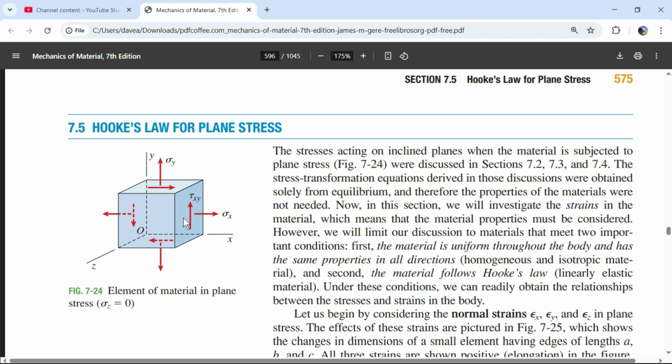All right, so this shear stress is on a face, and this face is in the positive x direction, and this shear stress is in the direction of the positive y direction. And so that's what we call a positive shear stress. And then over here, this one's on the negative x face, but it's in the negative direction. Those negatives negate, and this is associated with a positive shear stress. And then positive y face, positive x direction, positive shear stress. Negative y face, negative x direction, negative and negative becomes a positive shear stress. All right, that was brutal.